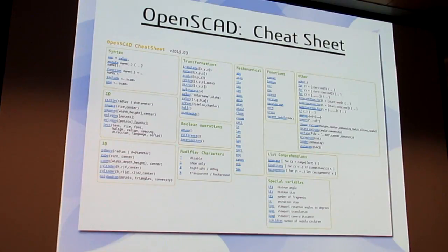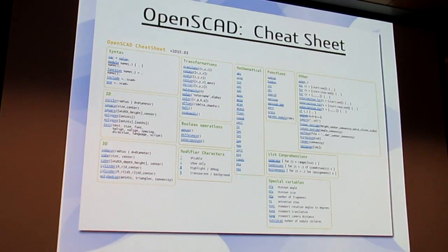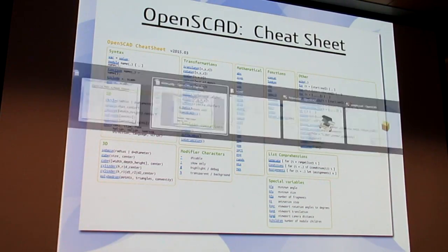Difference is a key one we're going to use, where you might take one object and use it to cut a hole in another object. So drill holes and things like that, you can use a difference to create those types of functions. We said it's algorithmic and parametric, so you get a whole bunch of mathematical functions. You can create equations to generate the parameters for the geometry, and a whole bunch of other more elaborate stuff we won't have time to go into here.